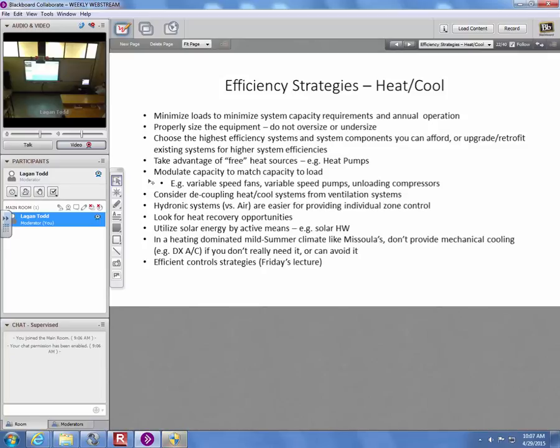The same thing applies to boilers. But let's say it's a hot water coil in an air handler, not a combustion piece of equipment. You can have a modulating valve that, if you need very little heat, just cracks open and allows a little bit of hot water to flow through the coil. As demand for heat increases, you start opening the valve more, and the valve modulates between closed and open to maintain. It's more of a constant maintenance rather than a periodic burst. Analog versus digital, that kind of thing.